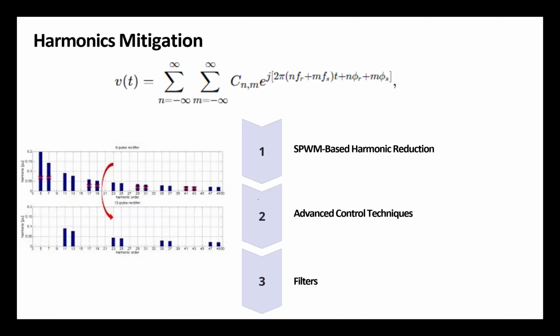Is that clear? So we have several parameters in our PWM system, in our PWM techniques, that affect the components of our Fourier series. The two frequencies, the two initial phase angles, and we already know that we have the modulation index shaping the amplitude of our main component. Are we good? Is that clear?